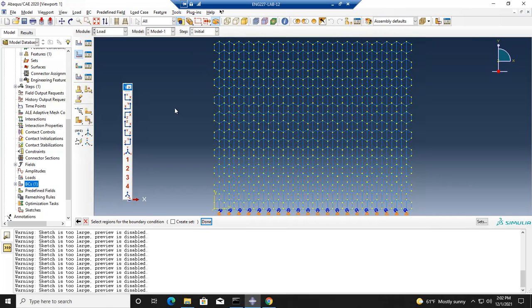But using the mouse and selecting so many at once, that will be the best way. Yeah, but in this case, it's not going to select all the nodes, it's still going to select the member because the nodes and the member here are interconnected. No, I mean, there should be some method to select only nodes. Let's figure out later. Okay.